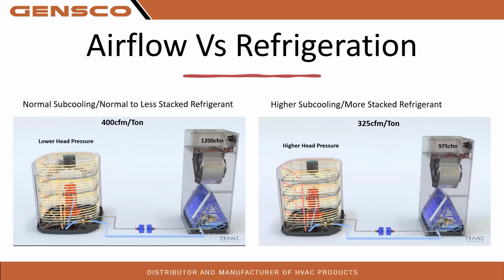But for those of you that have ever done total heat capacity loads, when you take wet bulb supply, wet bulb return, plot those on an enthalpy chart based off of your pounds of water, you're able to find what your total heat capacity is and then use your dry bulb.